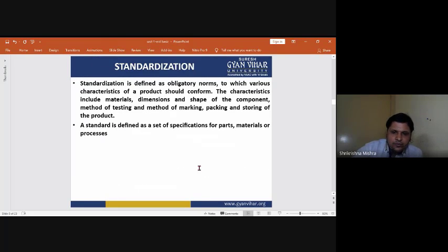All right. So there are standards for everything. As I have told you, standards for materials and their chemical composition, like IS 2110. This is a standard. It specifies seven grades of grey cast iron, designated as FG 150, FG 200, FG 220, and similarly the other names. The number indicates ultimate tensile strength in Newton per mm square. So these are the grades.